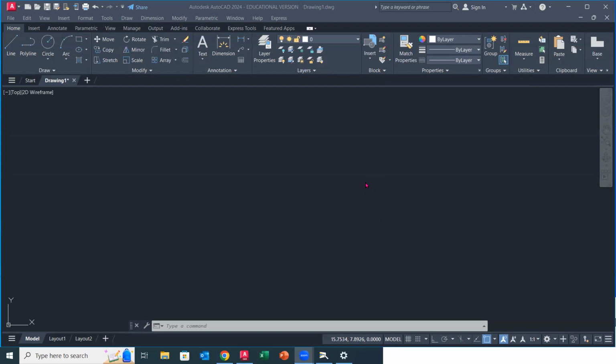But when we're starting out new, sometimes we want to set our perspective on our screen to what the units are going to be. Meaning, if I start drawing and my limits are set way out, my lines, even if they're 10 inches long, are going to be super tiny on the screen. Or if I'm zoomed way in on something that's 10 inches, it could be huge, or past the limits of the screen. So I want to give it perspective so that when I'm drawing, I can see most of the elements that I'm starting with.